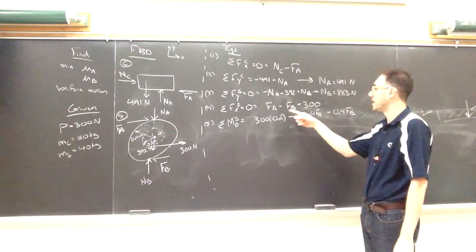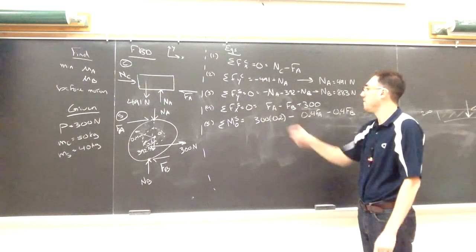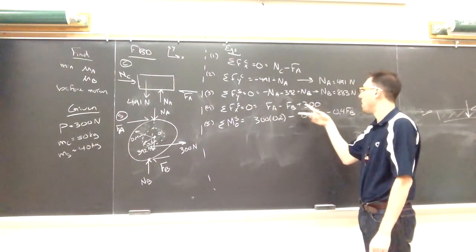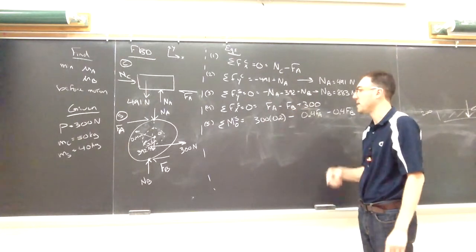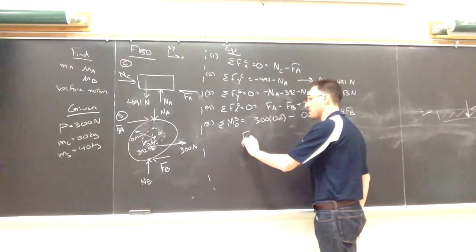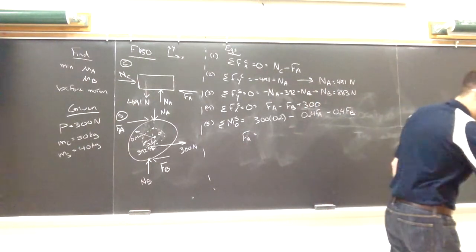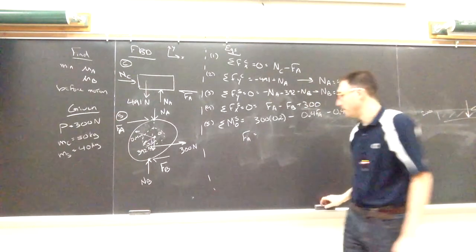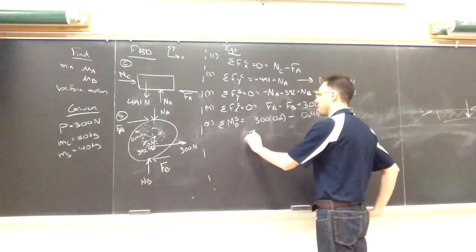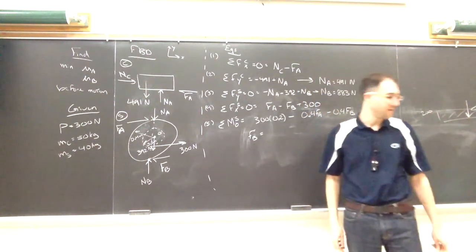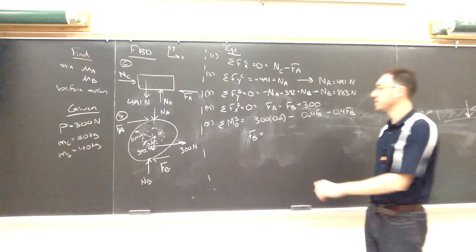And if we go through these, if we look at equation 5 and equation 4, between those, FA and FB are unknown. I can solve for what those friction forces must be to keep this in equilibrium. I'm going to solve FB first. If I solve this for FB, I get 225 newtons.